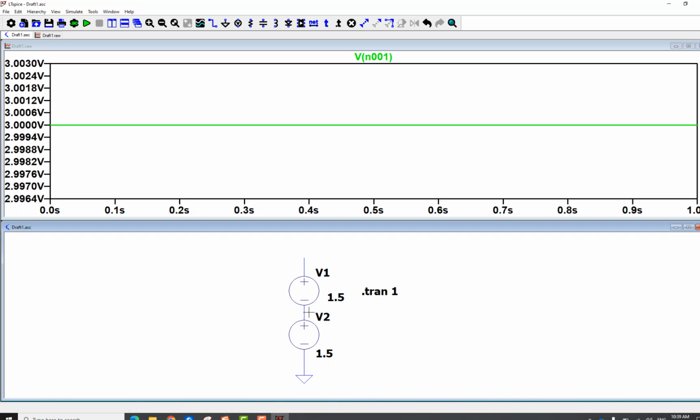And so, what's the voltage here? Still 1.5. It's not changing, right? So, if I ground it, let me see. Just some weird circuit here. If I ground this point, what's the voltage here? 1.5, yeah. What's the voltage here? 0, still 0. So I'm actually shorting these two terminals of the battery. So what's gonna happen? It's gonna burn which one? Burn the lower one, right? Yeah, that's not good.